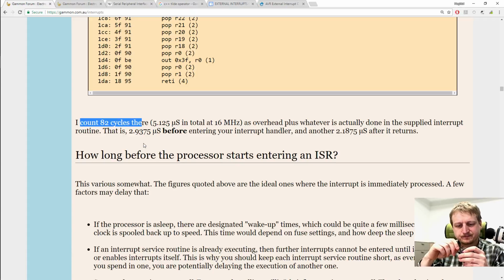If I had the tapper running the whole day, the lifetime of these servos would be gone in no time. I mean, I could change the servo every week because it would be going back and forth 24/7. You know, they are not built to do that. The servos are built to move a little and then pause for a longer time. Move a little, pause.